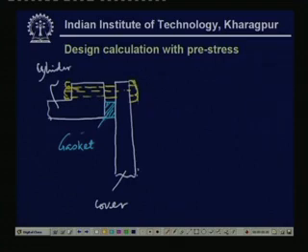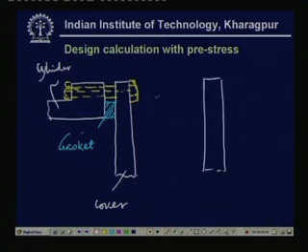So you use a bolt over here. Now we tighten it. The load taken by the bolt will cause some initial tension here. As you can see, whenever we tighten, then if you consider the free body diagram of this cover plate, as we tighten it by giving some torque, the force presses here, and the gasket also gives a pressure.